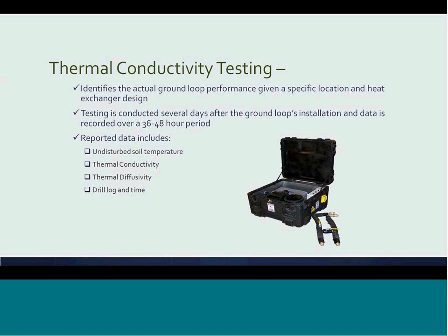Previously, we discussed the great diversity of soil properties in California. On larger projects, those in the 20 to 25 ton range or larger, it's a good idea to have a thermal conductivity test performed. This test is applied only to vertical loop systems. I've seen some cases where engineers are specifying thermal conductivity tests for horizontal, trenched loop systems, and I would caution you to understand what is behind this test, because